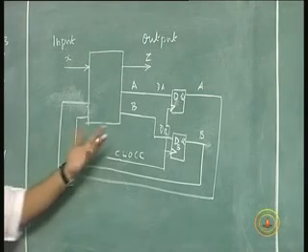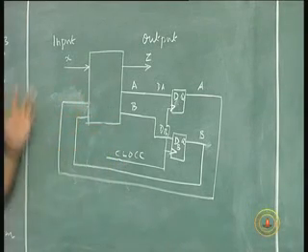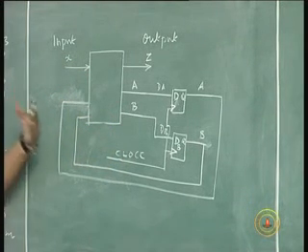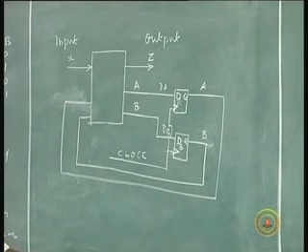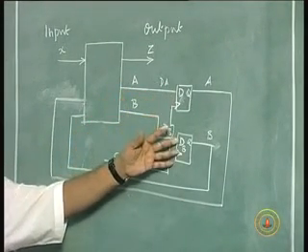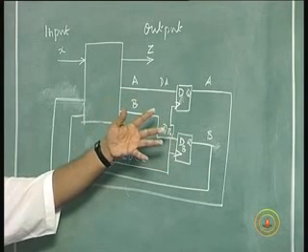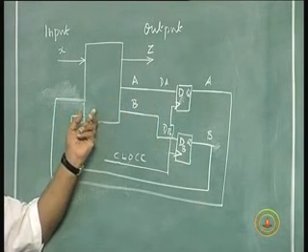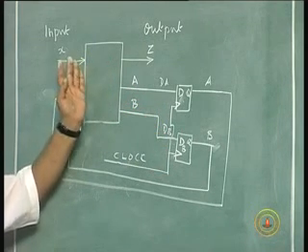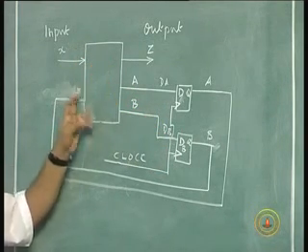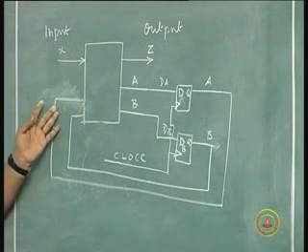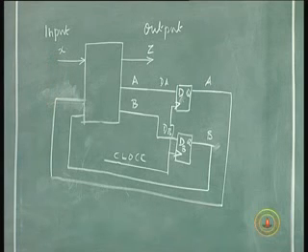So basically the whole circuit holds the whole scheme. This is the state machine or the digital system or whatever you want to call it. But this consists of two parts, very distinctly two parts. This is the sequential part which remembers the present state and makes it available for next transition. And this is only a transition circuit which determines what is the present state and what is the input, and decides what should be the next transition. So this need not be sequential. This is only a combinational logic, because I need to know what is the present state and I need to know what is the input, so that I can determine what the next state will be.